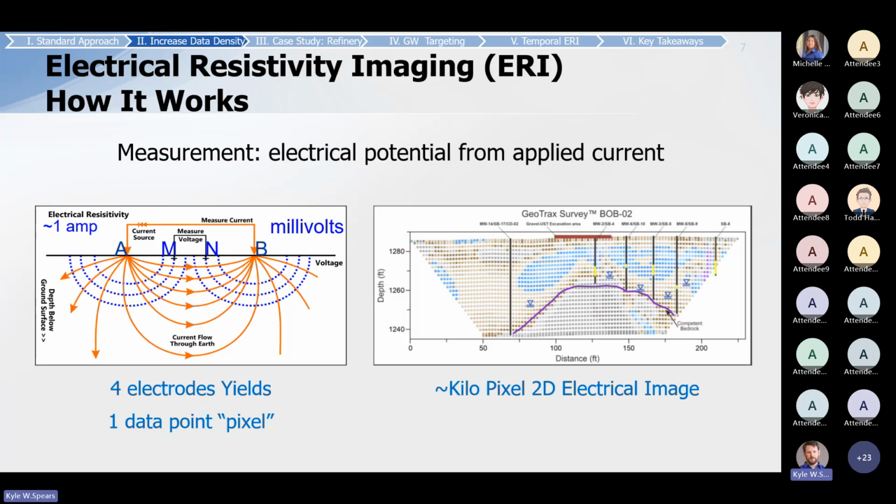So ASIS's scan is electrical resistivity imaging in its basic form. For those of you on the call not familiar, that's simply taking a series of electrodes, and you take two of them, you inject electrical current into the ground, create the electrical field you can see in the diagram there. Meanwhile, an instrument is measuring the potential drop with two other electrodes. This will be labeled M and N. So again, the current injecting electrodes are A and B, the electrical current injecting electrodes. And so every time you do that setup, you get one measurement.